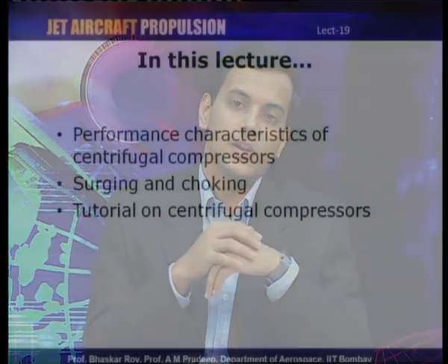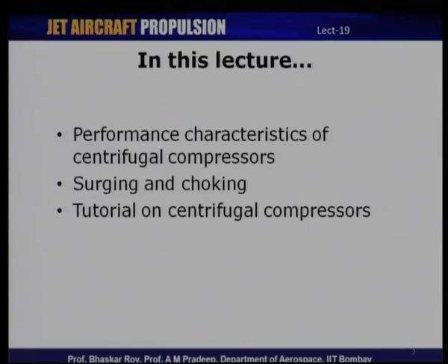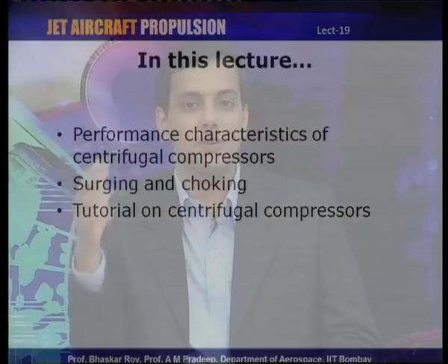If you recall, during our discussion on axial compressors, what we had realized is that the performance of axial compressors is a function of a variety of other parameters. That is, the exit or delivery stagnation pressure or the pressure ratio and the efficiency are functions of a host of other parameters like the rotational speed, the geometric parameters and so on, and of course, the mass flow rate.